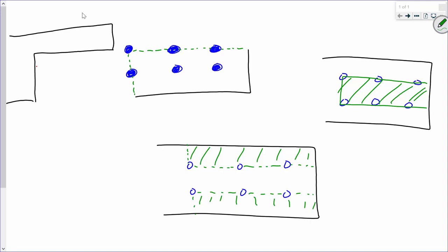And then in a plate, it ultimately comes down to which failure path you're given. Well, no, that's not what I'm saying. Look, for the plate that I drew up there, I've got 3 different options. All of them are viable failure paths. What I'm saying is whichever one has the lowest VRN, that's the one that governs. Think about it like this. If it takes 300 kips for this to happen, 400 kips for this to happen, and 200 kips for this to happen, this is the one that's going to happen. This is the governing path, all right? Think path of least resistance.